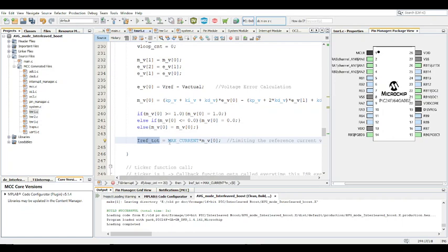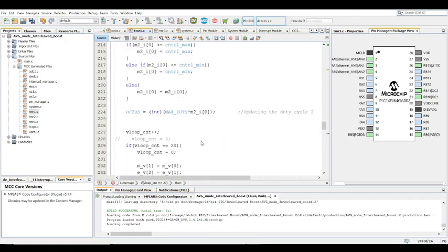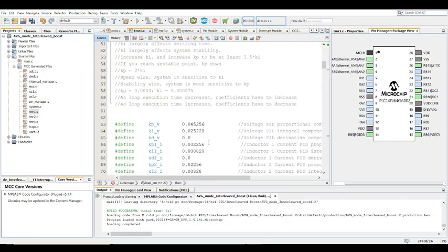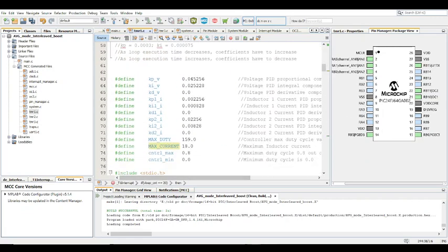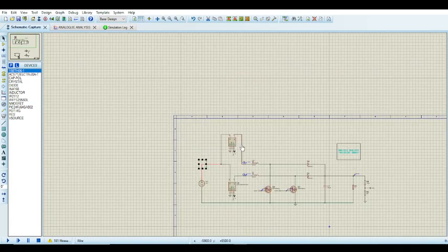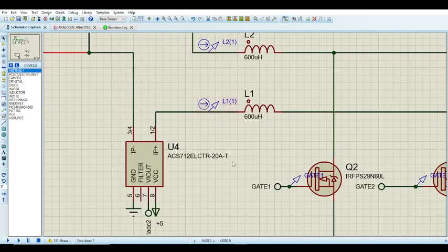So you have to scale that: the max current multiplied by the PID control output. In this case, I made the max current, which is the IRF total, 18, so only a current up to 18 can flow in here, which basically means the max current flowing through each of these channels is going to be 9, 18 divided by 2.